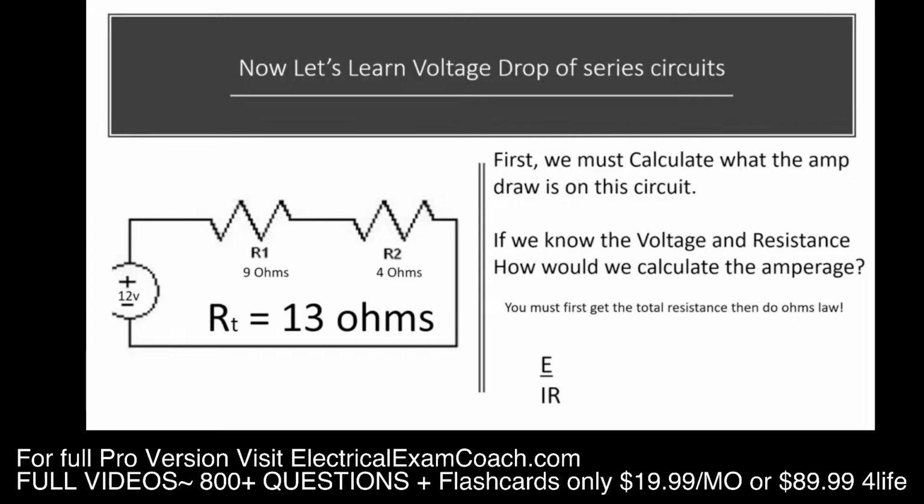So what we do is we set up our formula so we remember, and we plug in the knowns. In this case, we know that it's a 12-volt circuit. We got 13 ohms of resistance. All we must do now is to divide 13 up into 12, and that's going to give us our amperage. In this case, it's 0.923 amps.